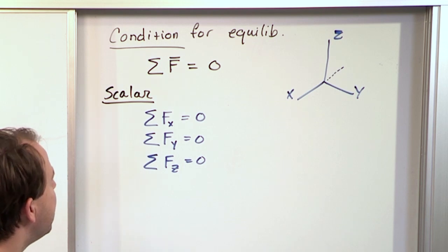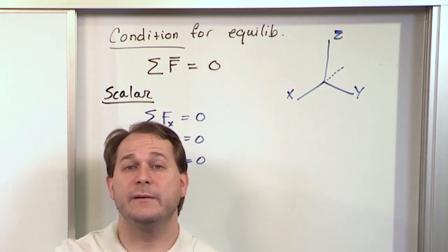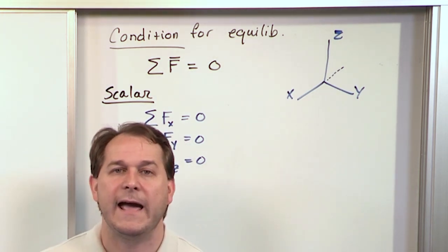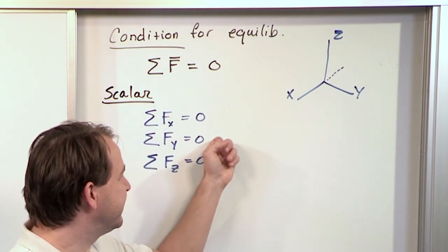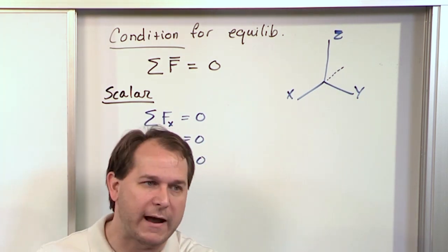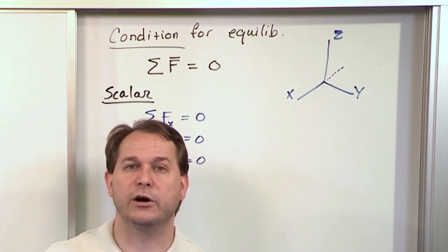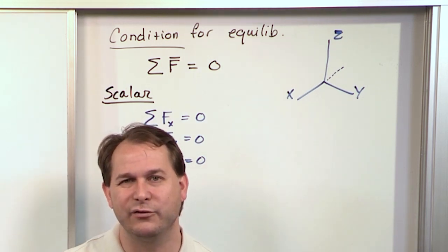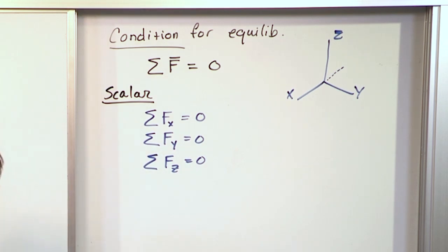as we're tracking things. So as we draw our free body diagrams, we're typically going to be drawing them in 3 dimensions. And as you write things down, if you end up using the scalar form of these equations, you need to keep track of whether your force is positive or negative, depending on your sign convention. It's the same as we've done in 2 dimensions, we're just extending it a little bit.